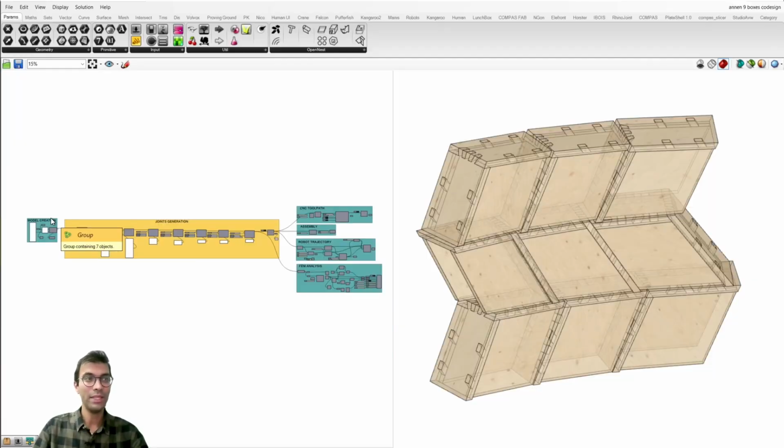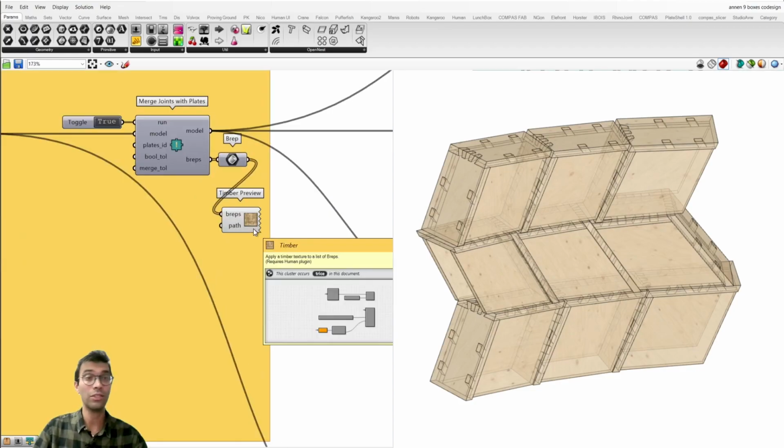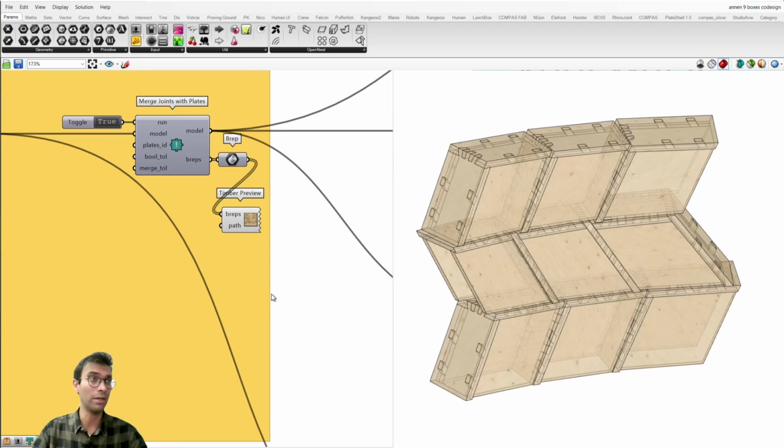Here is a geometry that Manis generated, and I believe in the previous video, my colleague Nicola already described the different modules. That geometry will basically serve for further finite element analysis. To reiterate what I explained in my previous slides, we need mid-contour polylines and also line elements in order to represent shell elements and connections respectively.